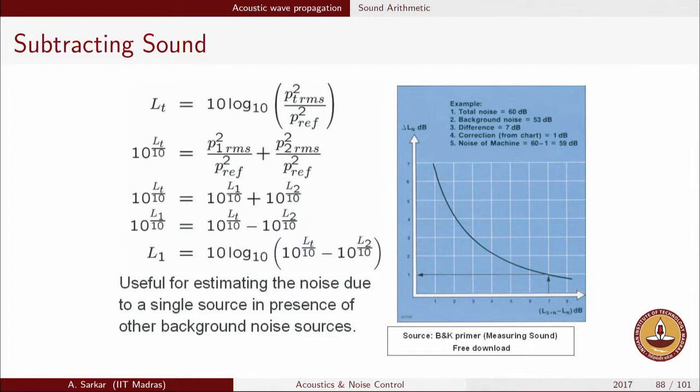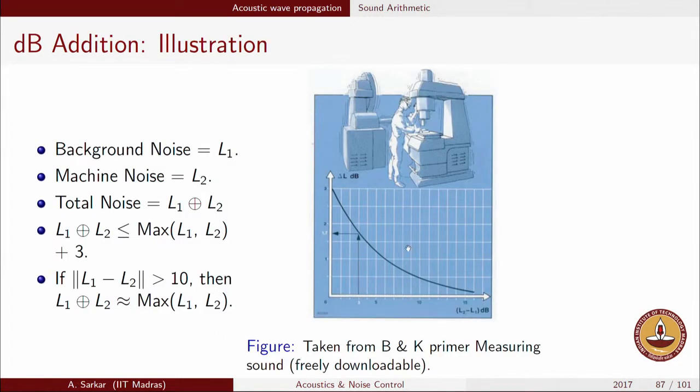total noise. Suppose you have in your machine two components, and both of the components, let us say engine and the transmission, both of the components are noisemakers in isolation, but the point is, at the vehicle level, when both the components are working, you should be able to identify which is the noisiest source. If it so happens that the noisiest source is the engine, and just to give you some example numbers, let us say the engine is at 90 dB and the transmission is